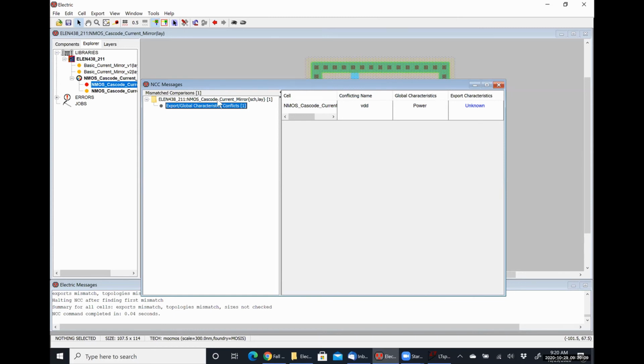So I'm pretty pleased with that, because that means it's treating all of the other exports correctly. It's recognizing our 3 transistors in parallel. All of the sizes match up. All of our technology matches up. So that's a pretty solid bit we have there.